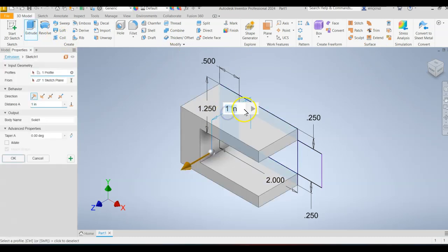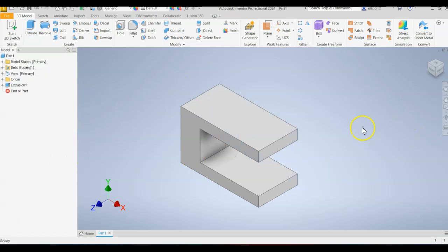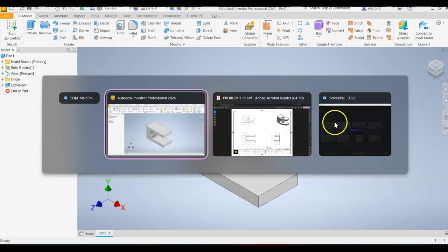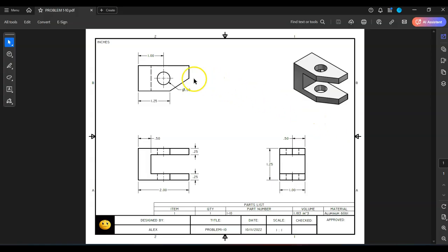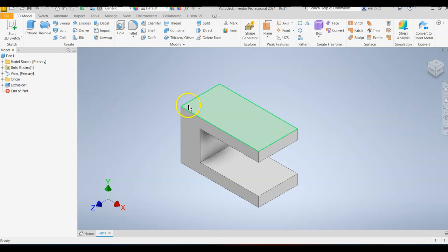click this U shape. It's defaulted to 1. Click OK. Bada bing, bada boom. Real straightforward. We have this angle that I want to cut away now, and that angle is 1.25 inches away from this surface right here. And then if we look at the right side view here, it's 0.5. So we don't actually need to know the angle, we just need to know those location dimensions.